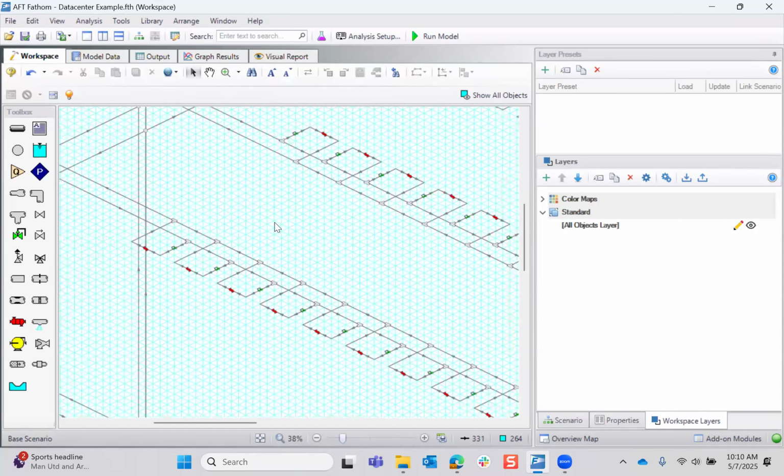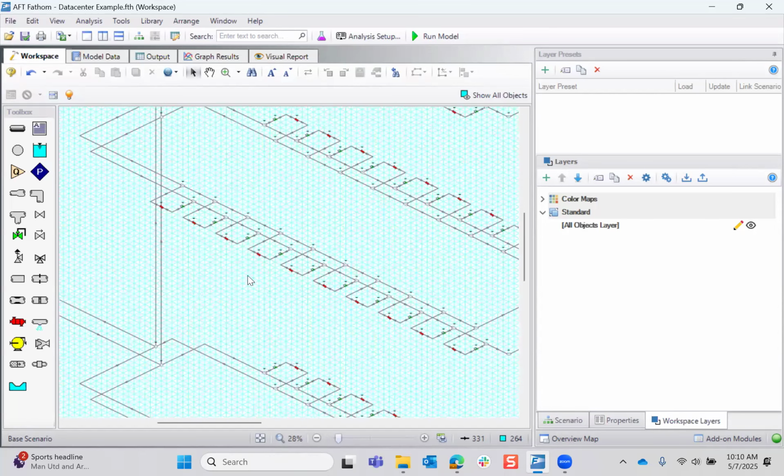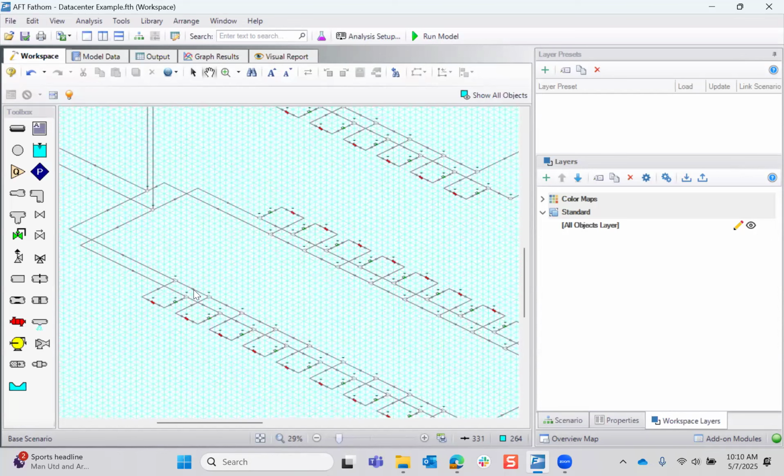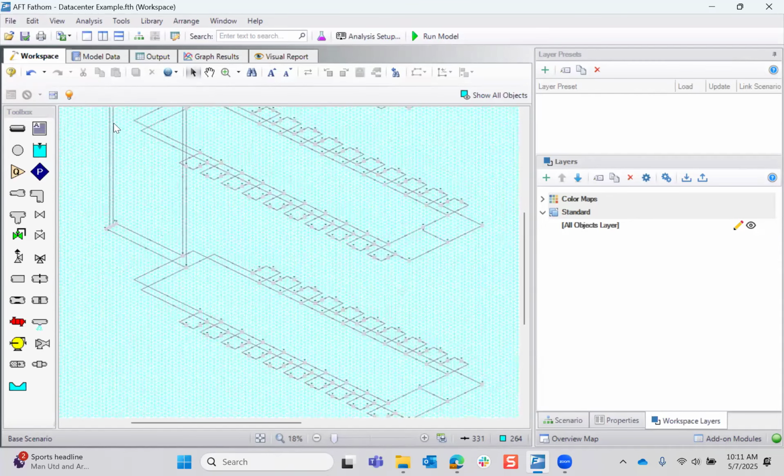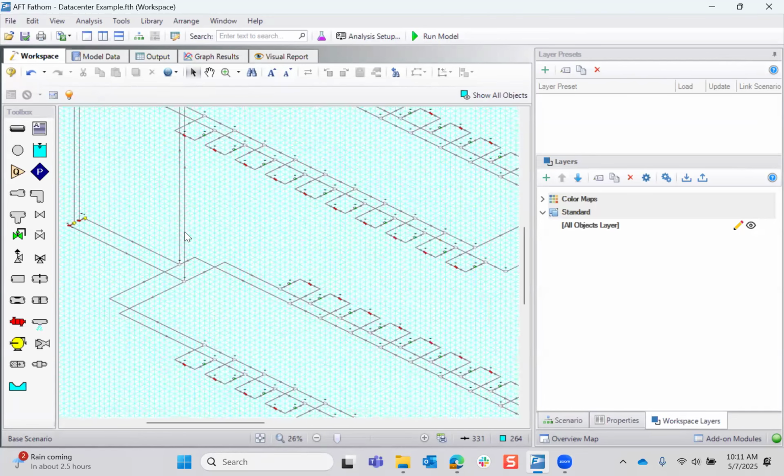The mistakes I had made were, one, I had just counted the flow to each of these air handling units, and then did the sum of all of that flow and just plugged it into the pump. But that's not actually how distribution of flow works in the system. You need a little bit of extra flow as it splits across the different resistances in the system. So I actually had to bump up my flow in my pump to get all of those control valves to be able to satisfy their operating points. That was what was causing a majority of the problems in the model, was just that single missized pump, basically.